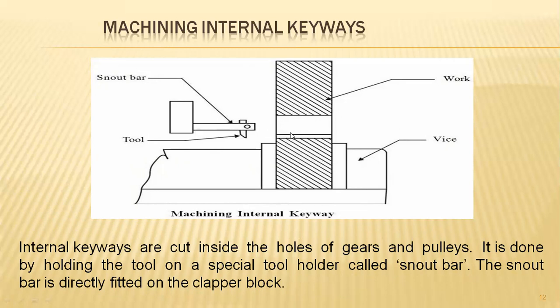For example, it has a particular length and a particular internal diameter, if it is a cylindrical object, and the diameter has to be increased. So you need to commence that activity based on one phenomenon of working. And the second thing is the slotter bar. The bar will remove material, the MRR process, towards only one direction, that is unidirectional. And in the reverse condition, it will have an idle traverse motion.